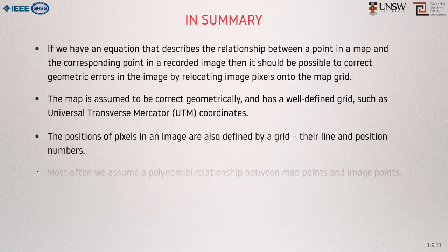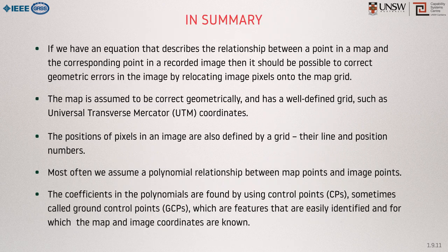Effectively, this technique depends upon having an accurate way of relating points in a map to the corresponding points in an image. We do this by the process of choosing control points and establishing mapping polynomials. We will see an example in a later lecture.